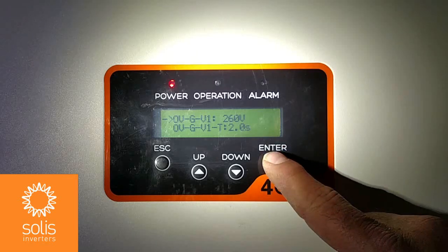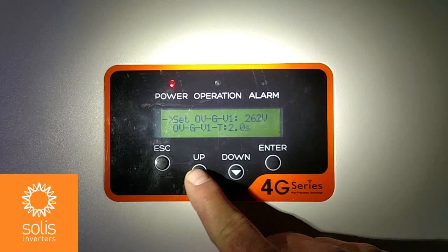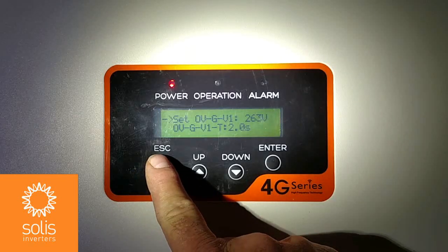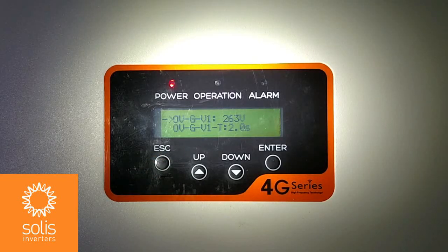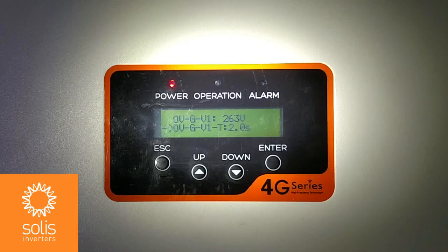So we can enter that menu and increase that to, let's say, 263. The buttons work a little funny here. We'll set all these later on, but right now use your escape key to go out. We can go down to the intermediate grid voltage trip time of 2 seconds, and that sounds good. Per IEEE, that sounds pretty good.